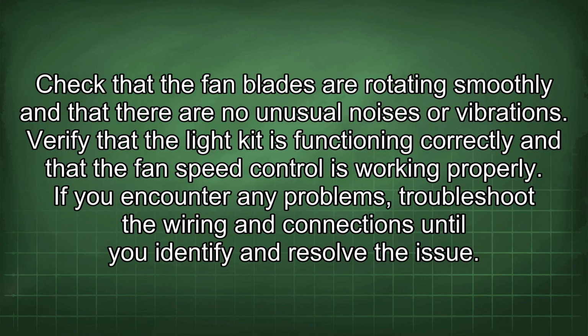Check that the fan blades are rotating smoothly and that there are no unusual noises or vibrations. Verify that the light kit is functioning correctly and that the fan speed control is working properly. If you encounter any problems, troubleshoot the wiring and connections until you identify and resolve the issue.